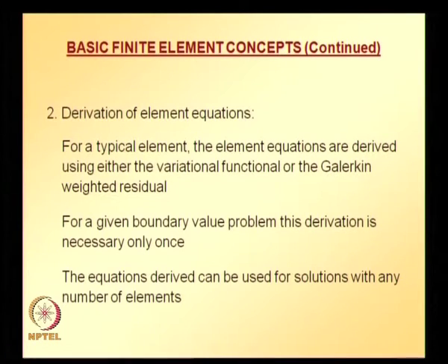whereas this kind of thing is not there in the earlier procedure that we followed. What we did in the previous example, where I demonstrated using the finite element technique, there we derived equations separately for each of the elements, element 1 and element 2, whereas here we are going to derive for a typical element. The equations derived for this typical element can be used for solutions with any number of elements.